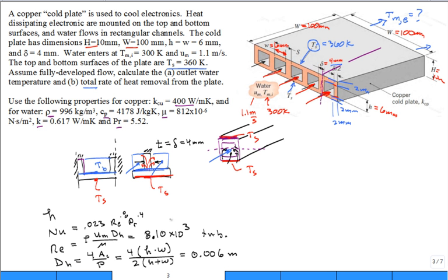When we calculate the Nusselt number, it comes in right at 61.0. I also calculated it using, I usually subscript something like this, Nusselt Dittus-Boelter, and then I'll compute the Nusselt number from that other correlation. I'm going to mispronounce his name, Gnielinski's correlation. When you calculate that, it comes in at 59.7. There's not much of a difference. These are basically the same numbers. So the two methods give the same Nusselt number, and we can unravel the Nusselt number to get the h.